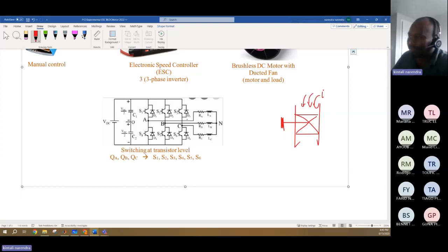In the same way, what we do in inverters is switching. We control the switching of these MOSFETs. You are providing a DC power supply here, and that voltage appears here. Now the switches S1, S2, S3, S4, S5, S6 are given to a microcontroller.